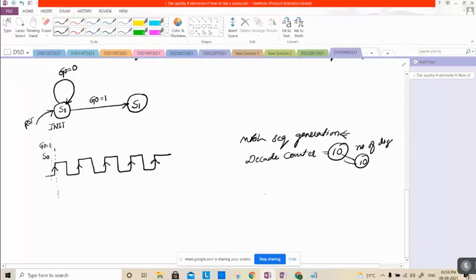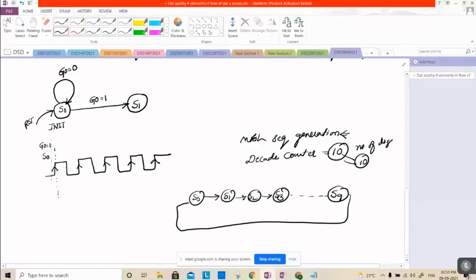So what will happen there is, how many flip-flops will be there in a decade counter? 4, sir. 4, right? S0, S1, S2, S3, and so on up to S9, right? So it is represented with Q3, Q2, Q1, Q0. Each state is represented with 4 bits, and there will be 4 flip-flops. Now, what is the purpose of the states here?